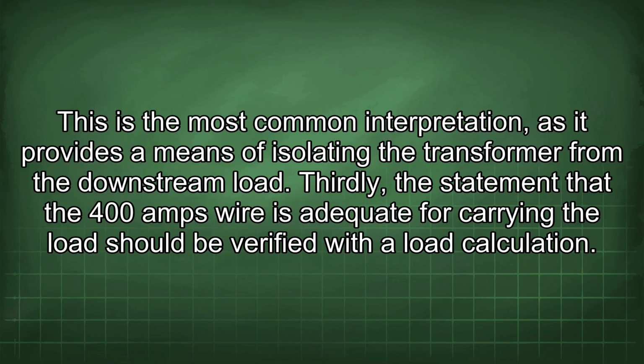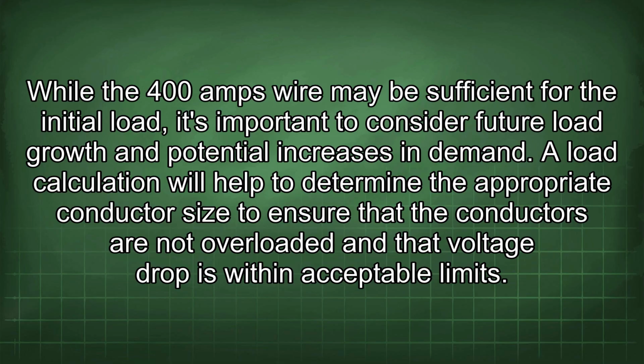Thirdly, the statement that the 400 amp wire is adequate for carrying the load should be verified with a load calculation. While the 400 amp wire may be sufficient for the initial load, it's important to consider future load growth and potential increases in demand.